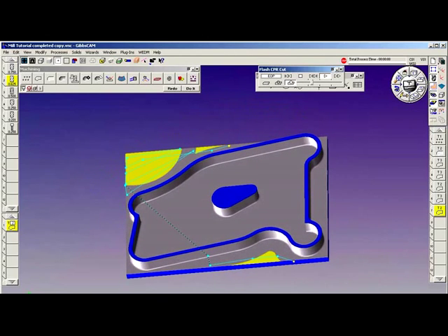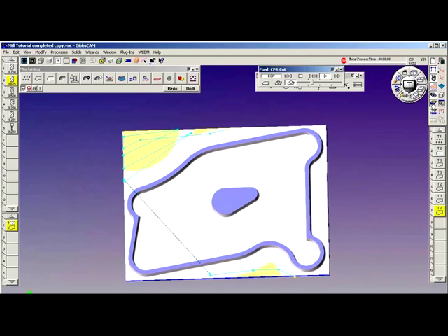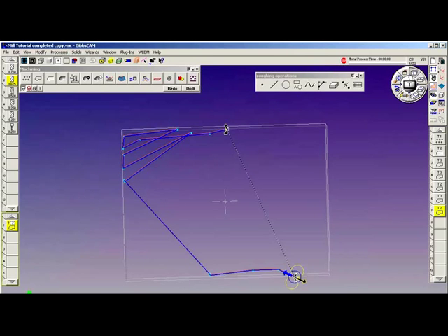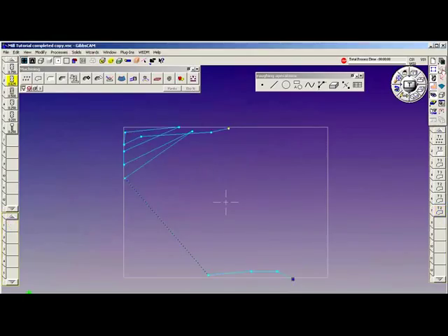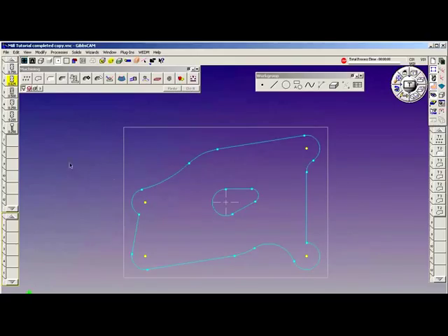All right, a couple more things to do, and we'll be wrapping this up shortly. If you're getting a little impatient here, turn off rendering, go back to top view. Next operation, we're going to spot, drill, and tap the 4 holes. So the first thing I'm going to do is deselect the operation, dump my process, open my work group list, and go to work group number 1, which is the original geometry. I'm going to make a multi-tool process. So once again, I bring down my spot drill, drill, and tap. I staged them all at the same time on this occasion.